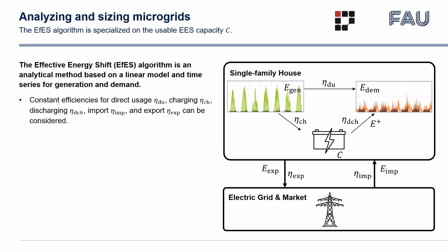On top of that, in this current publication, included are an efficiency for exporting energy and an efficiency for importing. In many systems, those are most likely one, at least the eta for import, but not the eta for export. If you want to export, for example, from your PV to the market, there's at least one inverter in between, which has its internal efficiency metrics.